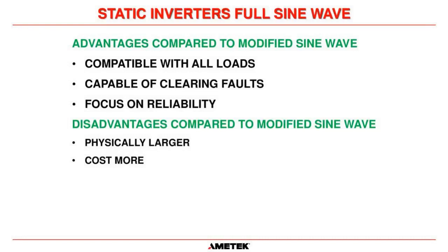They don't clear faults. And these are actually the advantages of the full sine wave inverter. They focus on reliability. Full sine wave inverters are physically larger than the modified sine wave, and they cost more. So the modified sine wave types are generally used in commercial buildings for office applications, that type of thing.